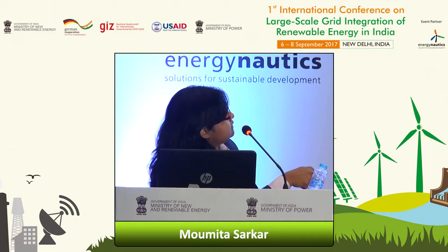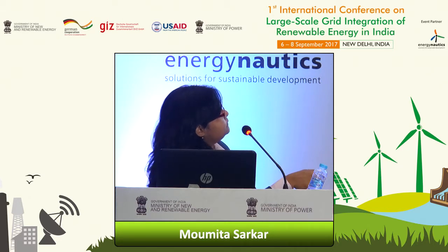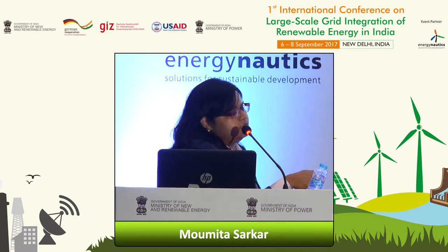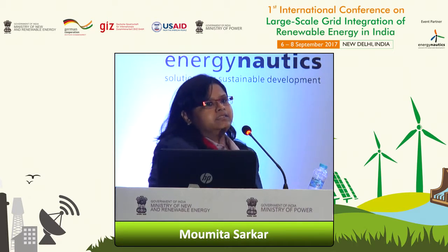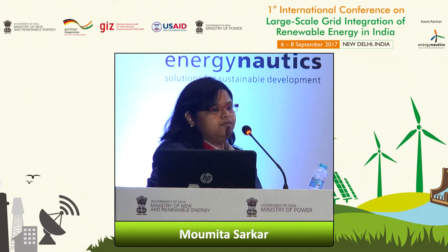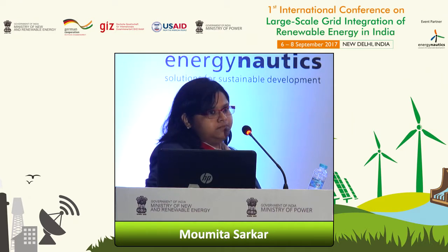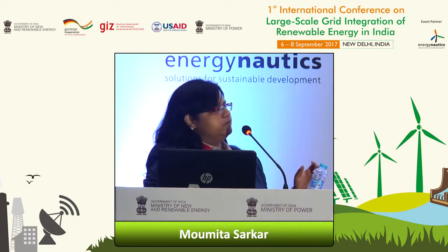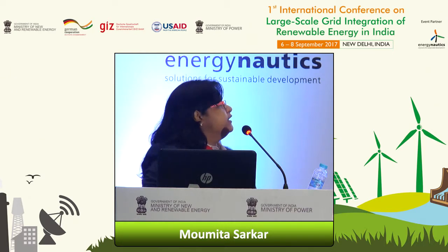But we can see that the active power remains constant throughout this study. This is because type 4 wind turbines are connected to the grid through back-to-back fully rated converters, which makes it possible to decouple the wind turbine generator from the grid, and also assists in independent active and reactive power control.